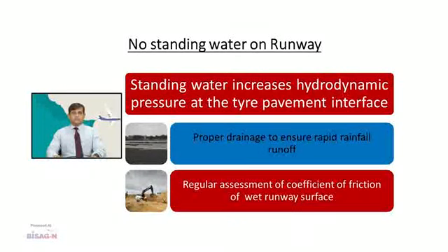We know that standing water tends to increase the hydrodynamic pressure at the tire pavement interface. Therefore, maintaining proper drainage of the runway is essential. In places where rainfall is high and in certain places where tides affect the drainage of water from the pavement, application of runway grooves may be considered to ensure rapid rainfall runoff.